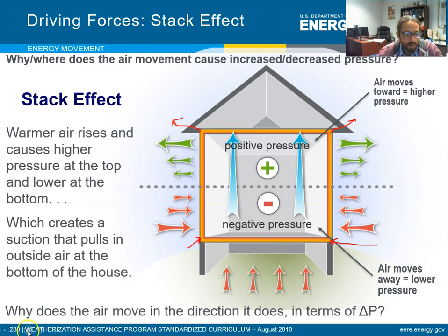Because remember, the air is just flowing from higher to lower pressure. And so it's higher pressure outside, it's flowing in. It's higher pressure inside up here, it's flowing out. And so that's why it's really important to have the very top of the building sealed and the very bottom.